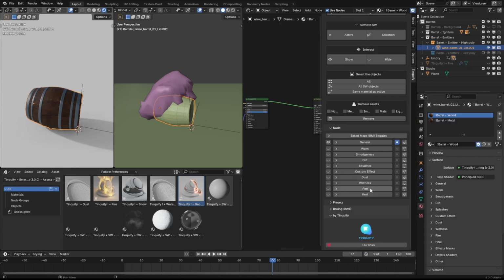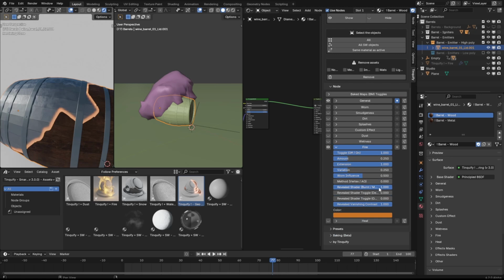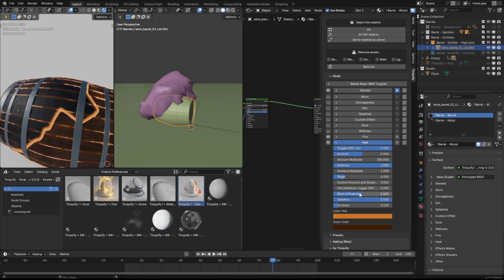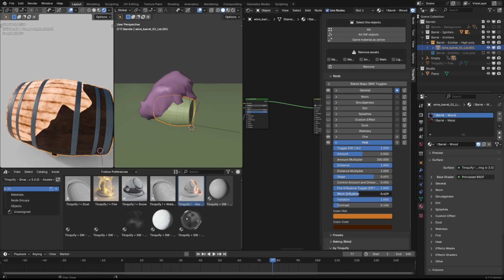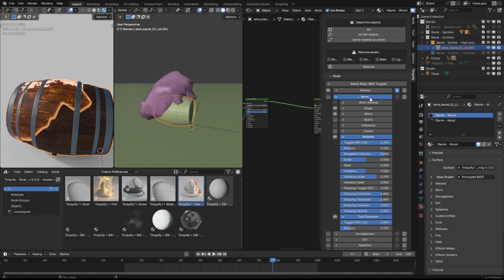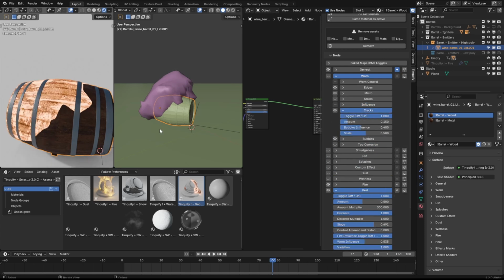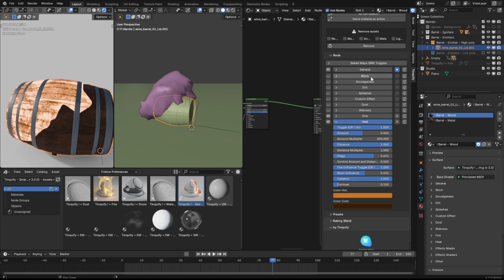And once I get the effect I want, I will add this helper and use a smart weathering shader node with the fire effect on. I will change the mode to burn instead of metal. I will enable the heat. I will add the fire influence, play a bit with the warm influence as well. I will add some bubbles in the warm effect, disable the top corrosion and top influence, and enable and play a little bit with the cracks to get the look that I want.